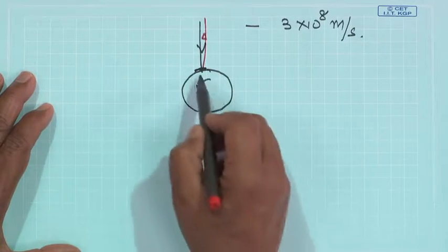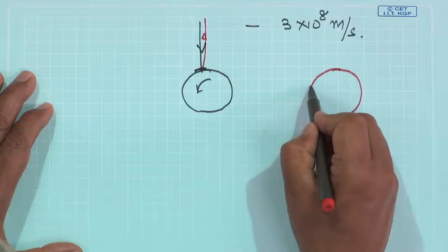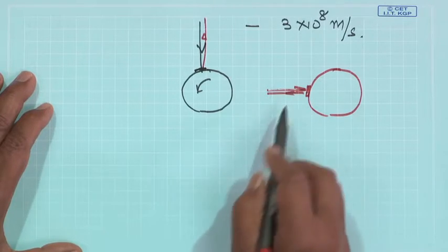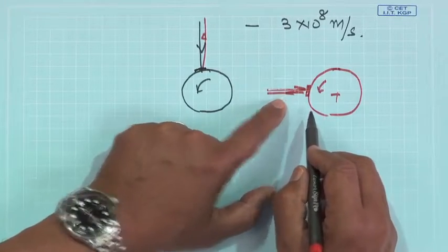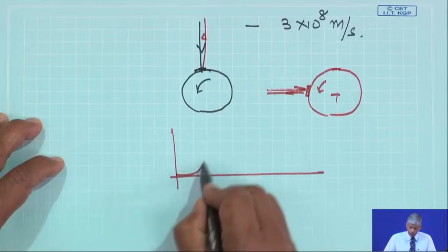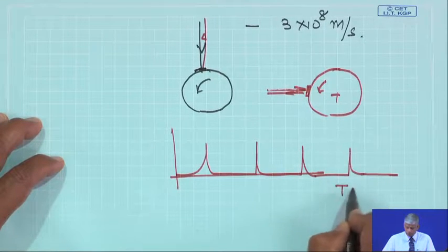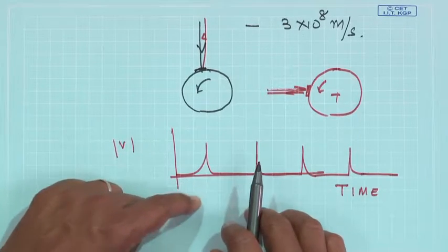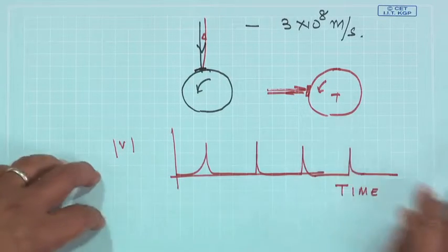And if I put a reflective tape on the shaft, instead of a reluctance type pickup where we looked into the magnetic field, here I will again get a voltage pulse, but this is due to the optical effect. Again, by measuring the time difference, I can measure the speed at which this is rotating.